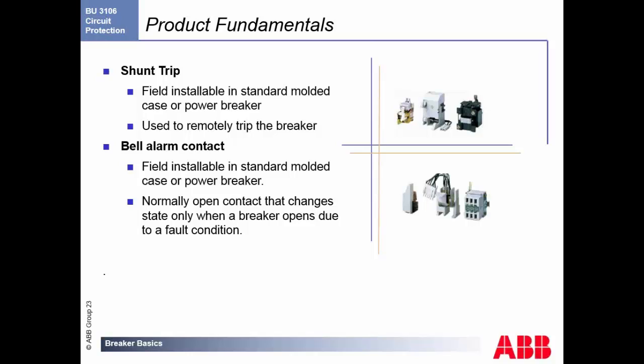Our shunt strip is also available. It's field installable, so you never have to go towards the service power. You can actually take off the face of our breakers, and you can use these low voltage breakers, shunt strips, and what have you to add more product features, and fundamental applications can be covered by the shunt strip. So basically, as soon as you flip a switch, the shunt will see the current go through and open our breaker.